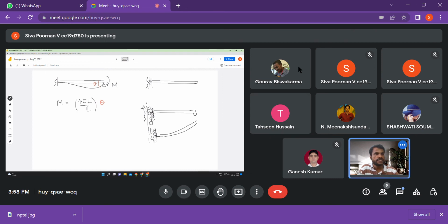Yes, so the plate that is attached to the beam will slide, but the plate will not rotate. The plate will still remain vertical. If it is allowed to rotate, then this total beam also rotates. So basically, this beam will always remain horizontal at the starting point. Only shear force is eliminated, and a fixed moment will still be there. So this deflection shape will be something like this at the point.